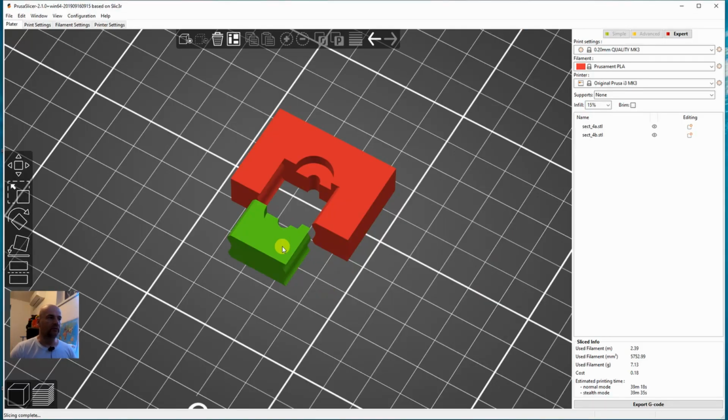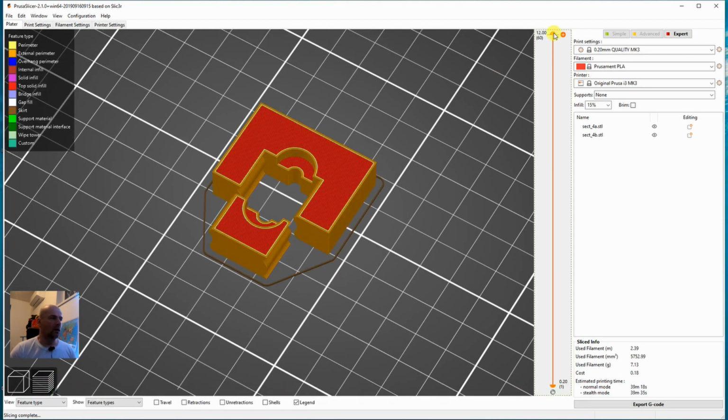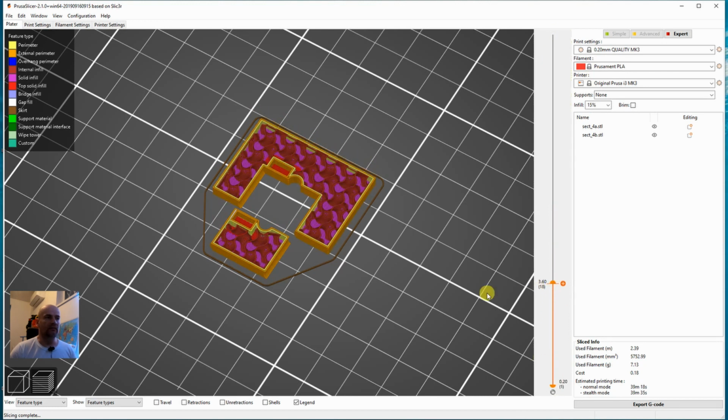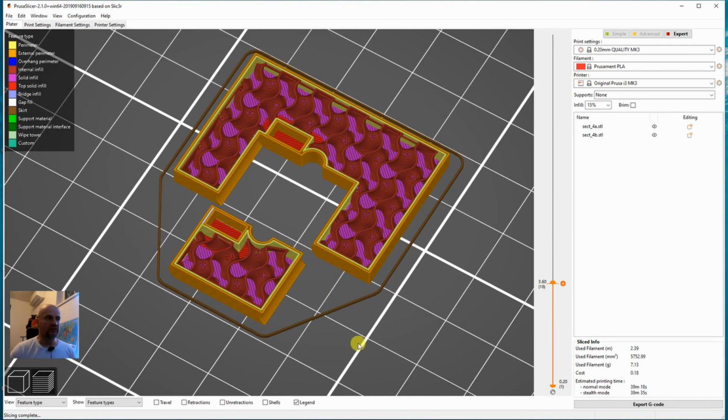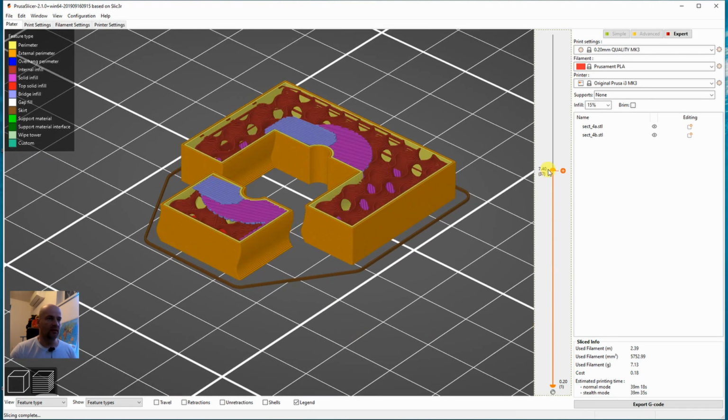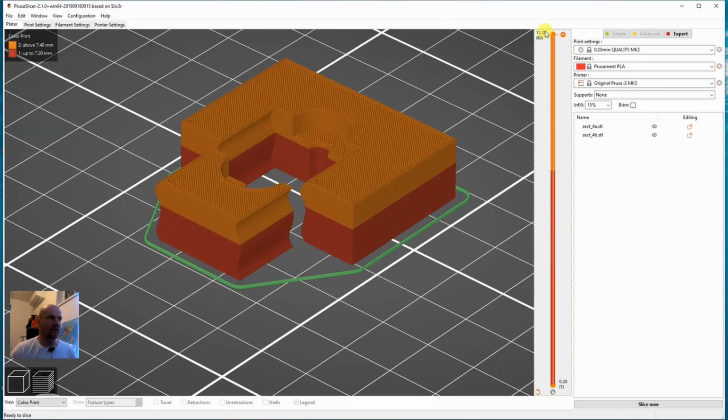These are 2 objects for the cutout section. I pulled this out because I don't want two magnets to be too close to each other. And again I have to add that filament change, which will be stopping the printing.